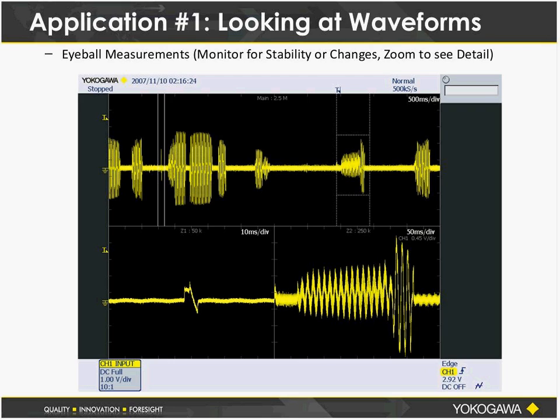In this example, we are looking at 5 seconds of a waveform from left to right. So we've got actually a relatively slower test. And usually when you're running slower tests, you'll see the waveform animate or roll from one side of the screen to the other. Now, maybe this is a startup test of a motor.